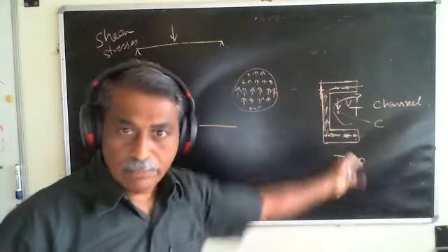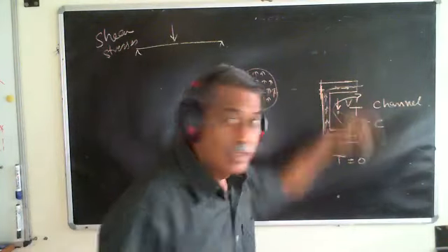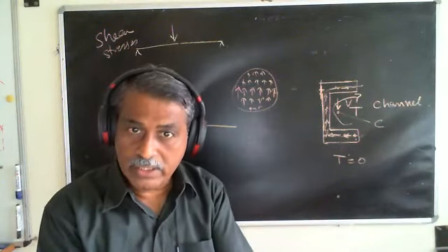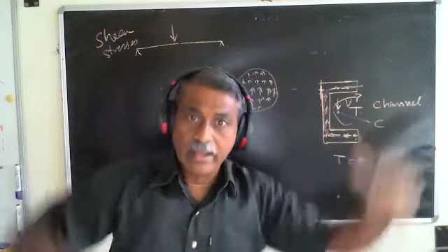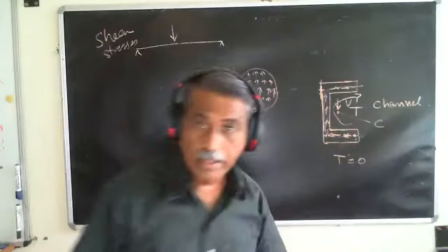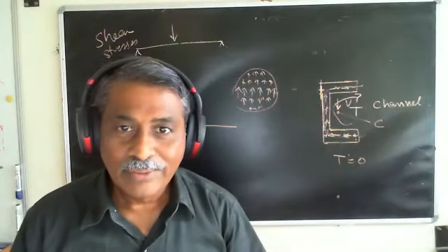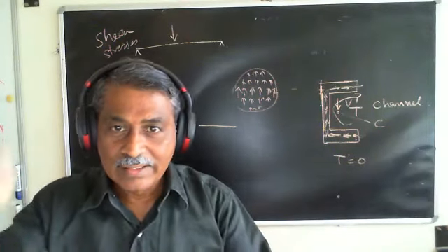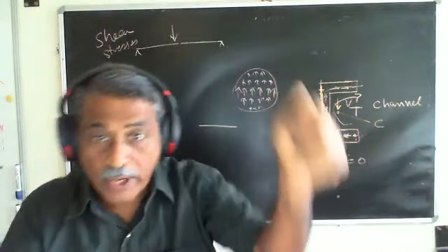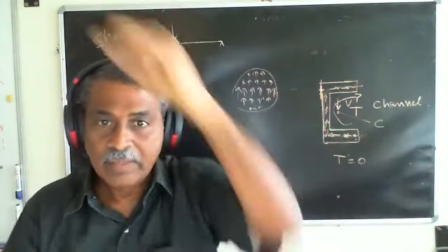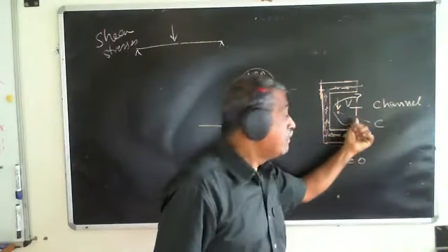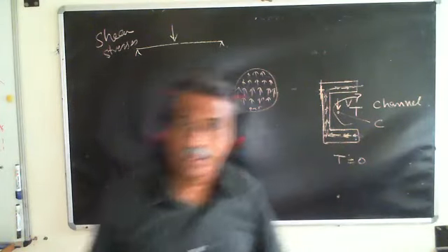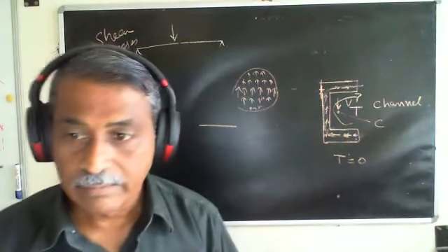right? And these internal forces will produce another twist to the beam. So if I have a channel section and I apply a load through the centroid, mind you, it will start to rotate because there is an unbalanced twisting moment occurring, right?